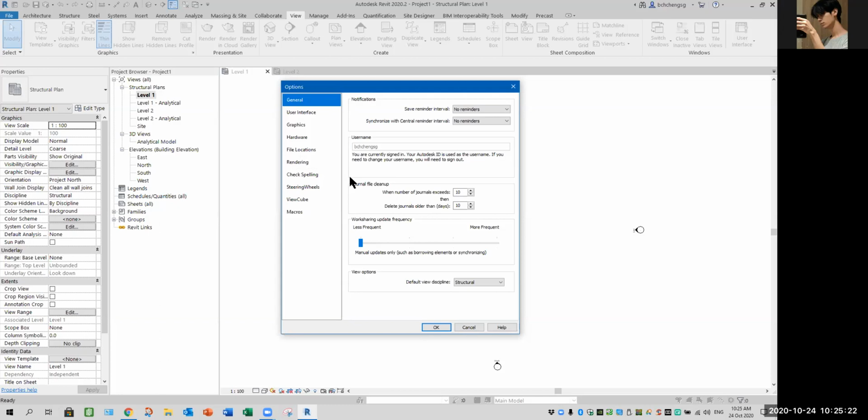When I'm in other BIM classes, I can switch that back to other stuff, right? Sorry, when I'm in BIM MEP, is it still fine if I use this structural? You still need to change. If you're taking MEP, you still need to change, provided if you are doing mechanical, electrical, or plumbing, because you are doing three separate projects and separate disciplines. So if let's say you are doing mechanical, which is HVAC, you need to select mechanical here. Same thing applies there.